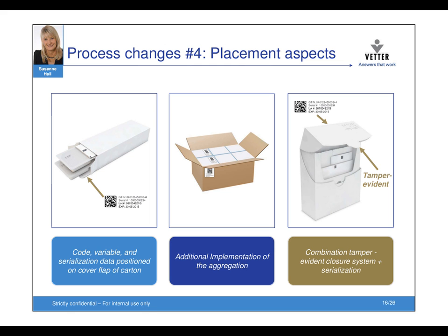If you need the aggregation, then you have to check how the folding carton is arranged in the shipping carton. The best way to do the aggregation is to have the camera on top of all numbers on the folding cartons already placed into the shipping carton. Depending on your equipment, you are able to aggregate in one layer or in additional layers on top of that. In some countries, like in Europe, the serialization always goes together with the tamper evidence of the folding box. There are several options for that. The different possibilities I will explain later.